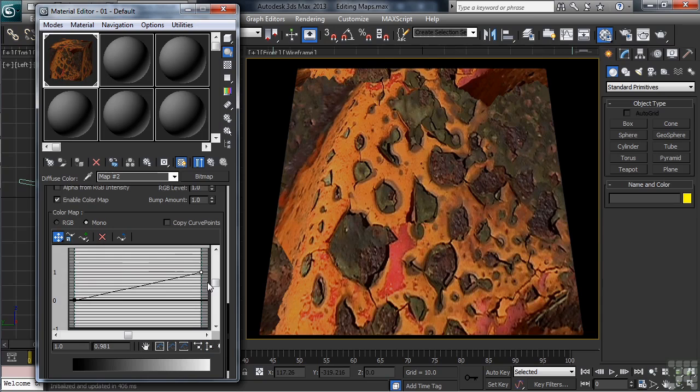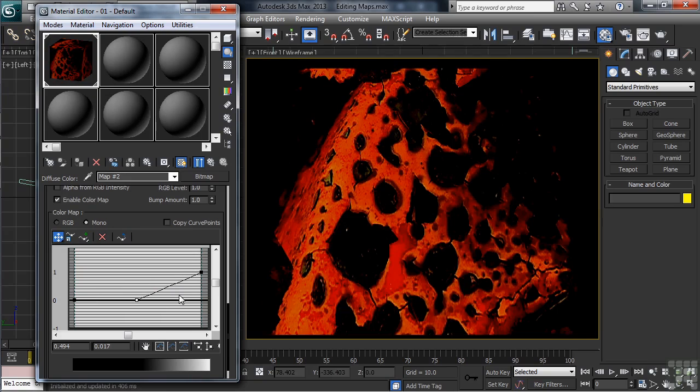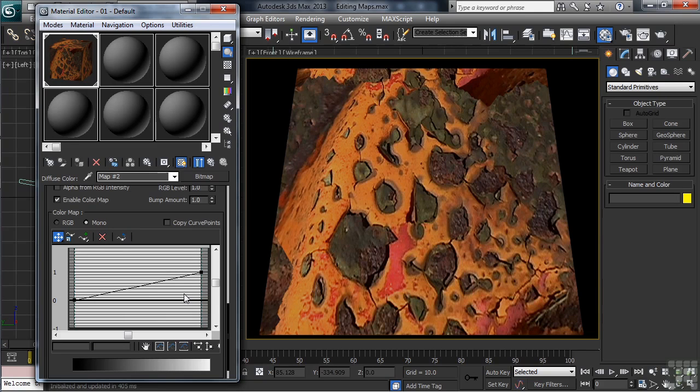You can also create additional control points within the control curve. Up on the upper left-hand side, you'll see an icon called Add Point. Let's click that, then add a point into the middle of our line. I'll then go back to the Move Control Point command, taking that point a little farther down. You can see the dramatic effect that creates. Let's go ahead and delete that point. What's nice about these handles is they too can be animated, which really opens up the possibilities.